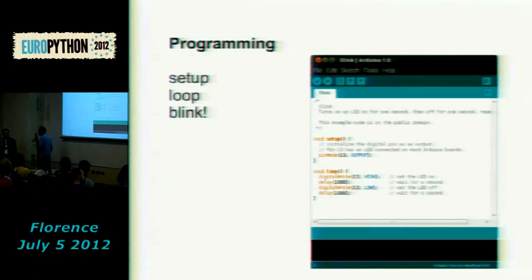It's not really difficult. This is probably the most important novelty brought to us by Arduino, because using the libraries and the IDE, we have very handy functions ready to use. We don't have to worry about manipulating single bits of registers, and there are a lot of checks and controls. Of course, the drawback is the speed. If you want to do something really fast, you should use bit manipulation, register manipulation, directly, because function calls in this kind of device are really, really slow. This is what I've experienced directly. So sometimes you prototype using these Arduino libraries. Then if you want something that works at a certain speed, you must rewrite the functions using register manipulation directly.